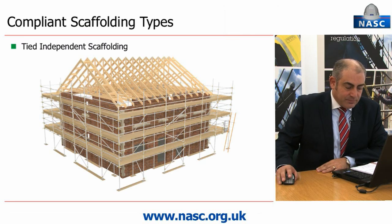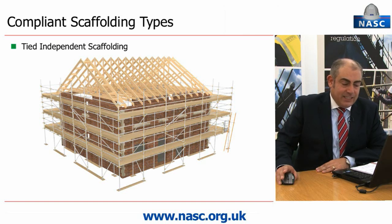Independent tied scaffolding. It features unclad, brick guarded, debris netted or solid sheeted. Bay sizes up to 2.4 metres. Note there is no 2.7 metre bay size included. We see the welcome return of single bay facade bracing without the need for additional plan bracing. Lift heights commonly up to 2.1 metres, but also accommodating floor height lifts up to 3 metres. Safe heights from the operational guide up to 16 metres, or scaffolds up to 50 metres from the eGuide.